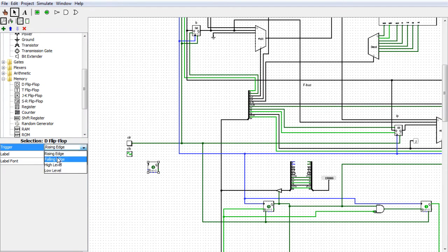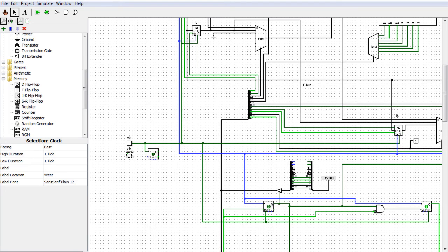It's gonna be falling edge sensitive, and the clock is actually going to be hooked up to the clear signal here. And I don't know if this is the best way I could wire this up, but I'm sure Robert will wire it up a lot prettier afterwards. Anyways, we're going to put the input of the clock into the data here. So now when we release the clear, this is going to acquire the current state of the clock. And we want to make sure that when we release, the output from here is always starting high. So we need a little bit of logic.